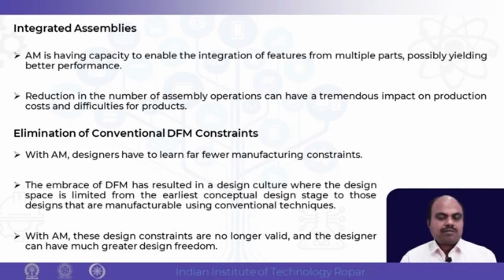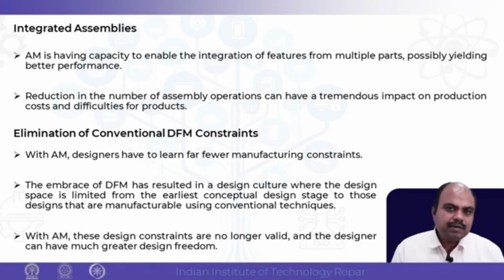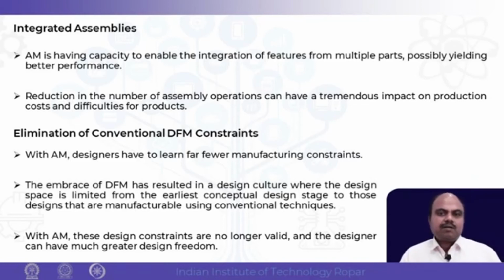So it is going to reduce the cost a lot. Of course, mass manufacturing using additive manufacturing is something which is still challenging. Now traditionally, design for manufacturing has a lot of constraints. Like, if you want to make rectangular slots, you have to think, how can I make it? So when a designer is giving a rectangular slot in the design, he may try to avoid it. But in additive manufacturing, those things are not there. So there are much fewer constraints.